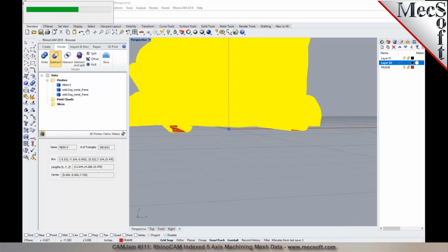Absolutely. Close that up and also put some clearance on that, because you cannot do a subtraction plus some three-dimensional clearance. You can model it in Rhino too. So that's the nice thing. You can create a solid model in Rhino and then convert it to a mesh and do a subtraction. So you can do mesh booleans in here.